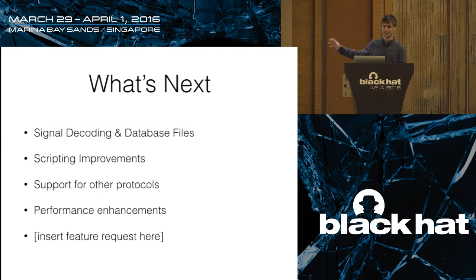So this entire talk has been about automotive. I'm sorry if you were expecting it to be about SCADA or about something else. But CAN is used a lot in SCADA systems. It's used a lot in motor control systems for industrial automation. They use protocols like CANopen, and there aren't too many good tools for working with CANopen other than proprietary stuff. And most of those are a pain too. I had one project I was working on where we had to do CANopen. It was not fun. We basically wrote our own tool was the solution. So to support those would also be useful for people doing different stuff with CAN that's not automotive.